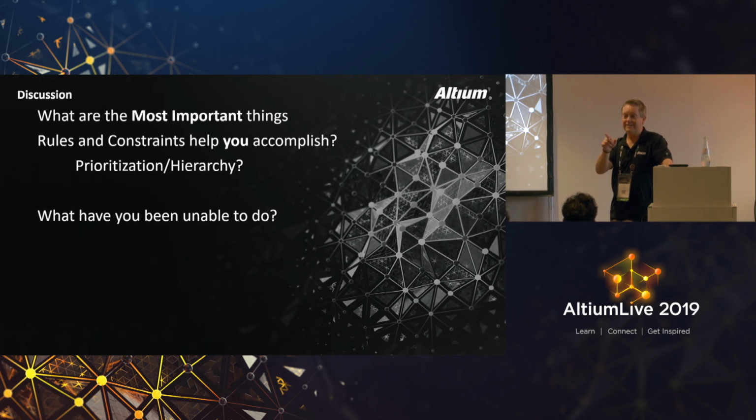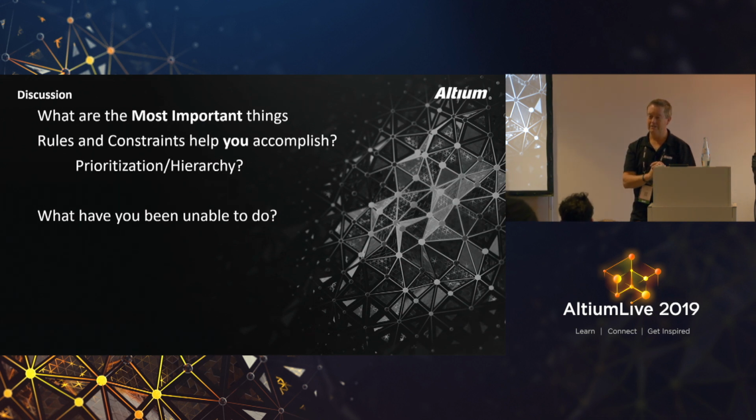We define this directly in the footprint, and not through the design rules. Yeah, I agree with you there. That's just something that came out recently. I wish I had added a slide for that, because you can pick one pad and just say, flood this pad, and that is really convenient when it just needs to be one or two things and not broadly across the whole board.